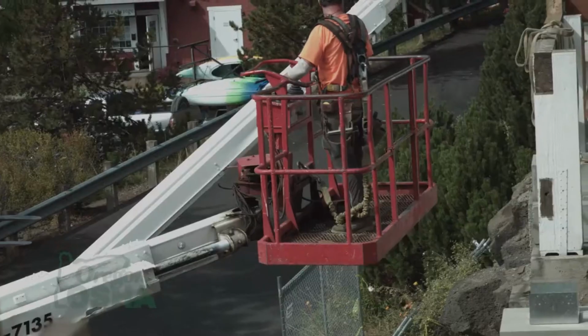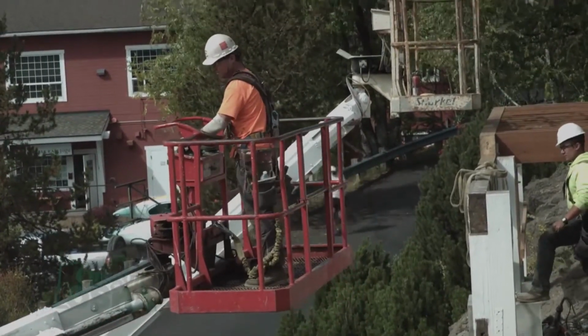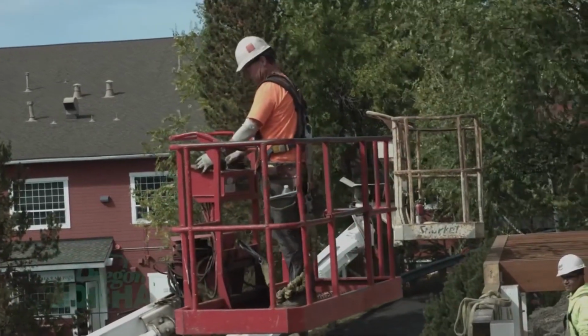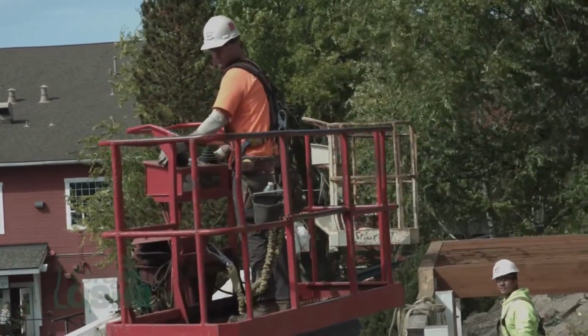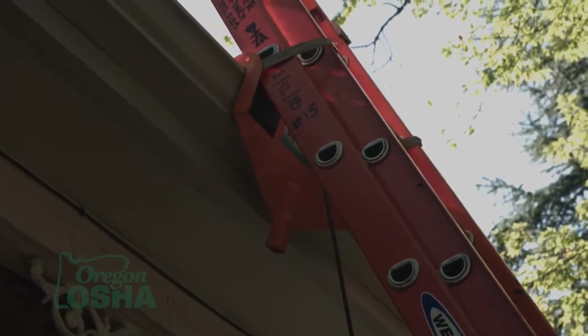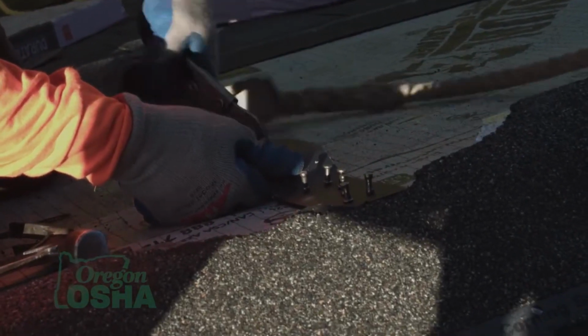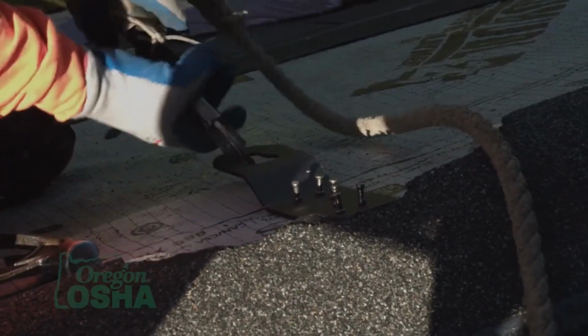Probably the way that we recommend doing it most often, if it's available, is establishing that first anchor point out of some sort of an aerial work platform, a scissor lift, or using a ladder to access that location, and then work safely to establish that anchor point. When establishing that first man up, we definitely want the worker who goes up there to be doing nothing but establishing that anchor point for the workers that are going to be coming after, testing it, making sure that it is thoroughly going to meet the needs and requirements for whatever fall arrest system they're putting on there.